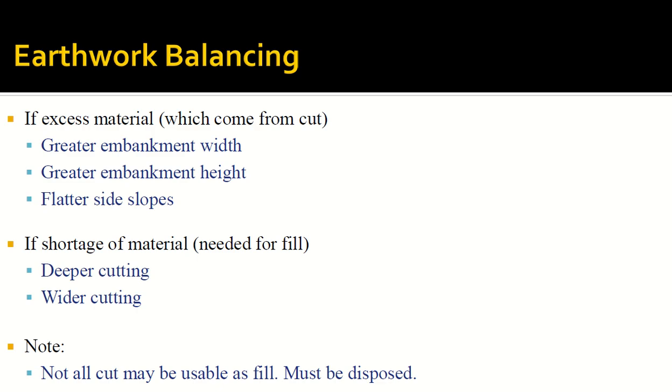So if I could use this 20 cubic yard, then I can fill 80 cubic yard with this material, right? So this 20 cubic yard now has to be disposed. So whatever material I have available on site, I need 20 cubic yard more to do the fill. Got it? So you have to subtract the unusable material from the fill, because you cannot use it for fill now. So it will not go in the balance. This 20 cubic yard will remain extra in the balance.